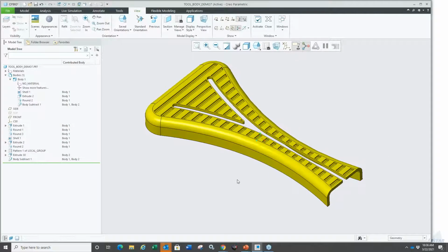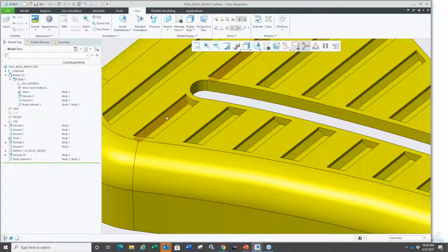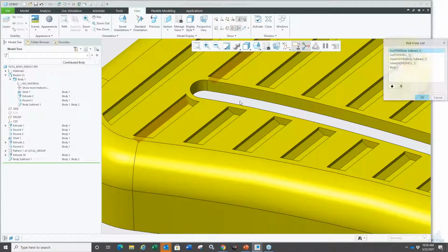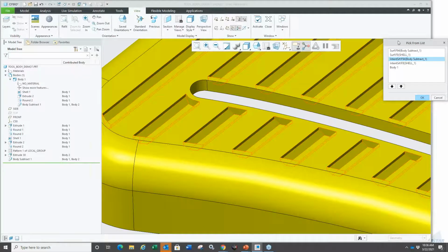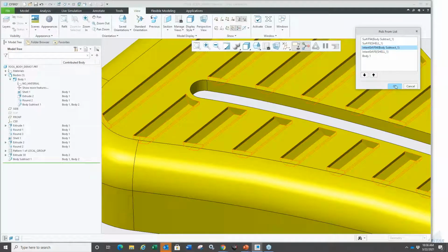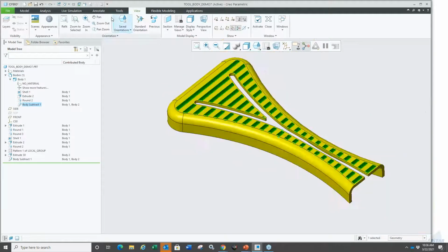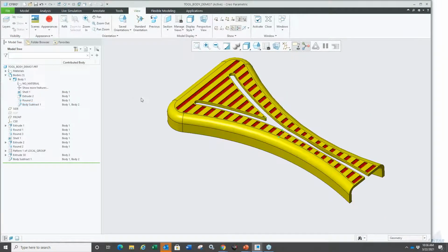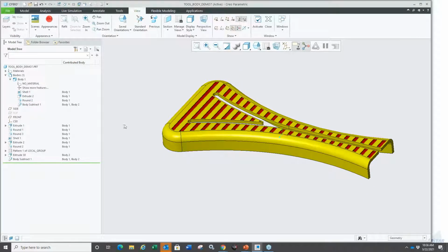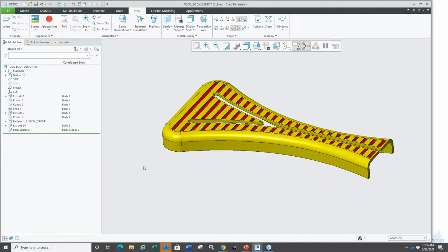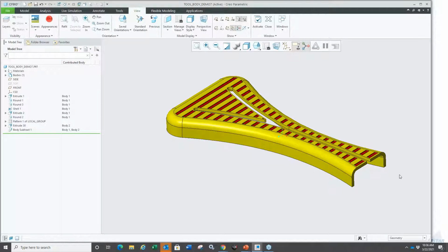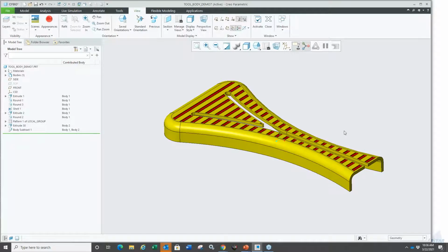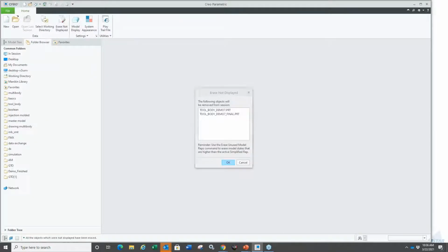There's your little body subtract, and it is consumed right now. Again, if I want to apply some specific colors to it, I could go to my query selection here. You have your intent surface for that body subtract. I'm able to select that surface and apply a different color or something like that. So you're able to do these types of geometries and features without using surfacing or remove. It's just another option here, so that might be helpful.